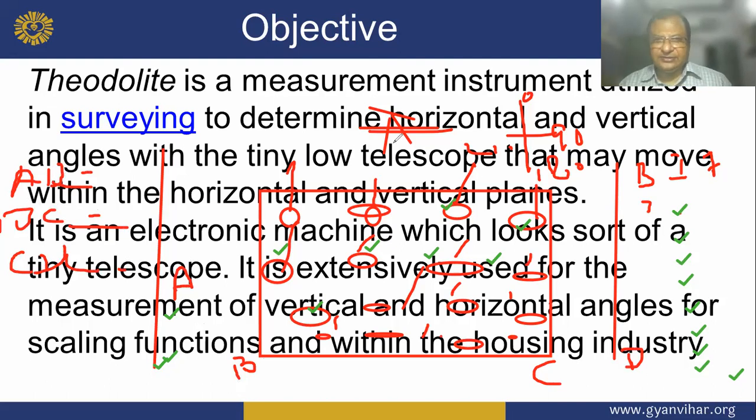and you have measured by stadia. Here you have fixed the point from stadia. You will stand a compass here and through the stadia constant you will find the distance of all these points. So work number 2, you have taken level, you have taken distance also.